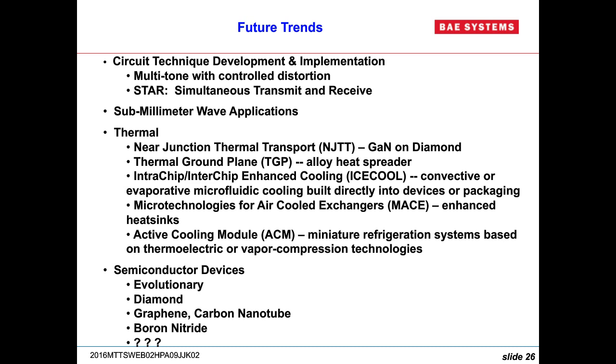But up until a few years ago, nobody could figure out how to do via holes in there. But now people know how to do via holes in diamond. But no one can figure out how to etch it or dope it still, which is necessary to make a semiconductor device. And because of that, it's still something that may be on the horizon, but a transistor hasn't even been built in it yet.